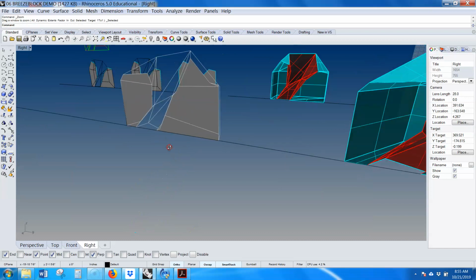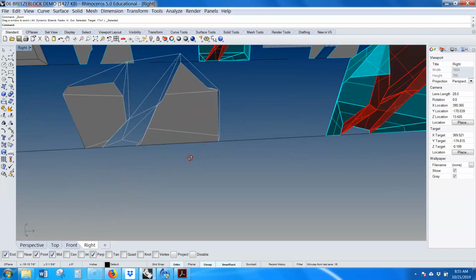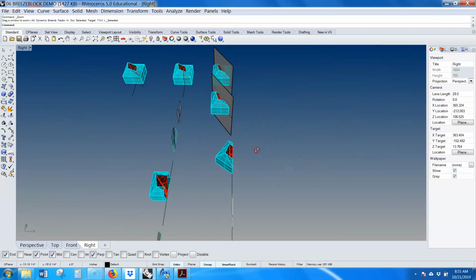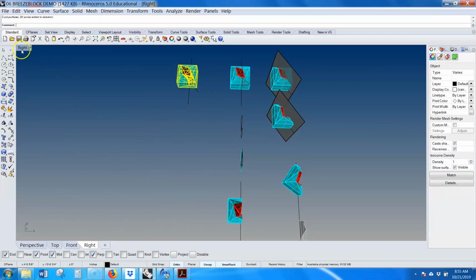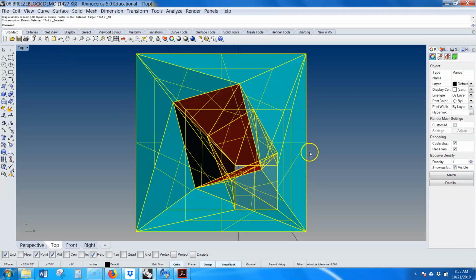Everybody got that? When we're cutting the section, it's just a line. Can we add some thickness, or is it okay if we leave it like that? I would just do that with line weights in AutoCAD. If you're suggesting it's a material, then you could actually model that. But because this is just a 12-inch module, just use thick and thin line weights.